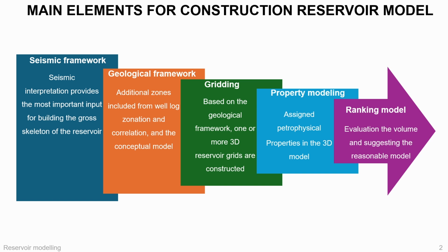This slide summarizes the building blocks. Seismic interpretation provides the major structural input, including horizons and faults. We then build a framework, create a grid, model facies, and finally populate petrophysical properties like porosity and permeability.